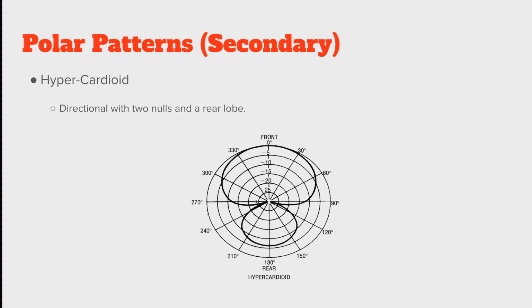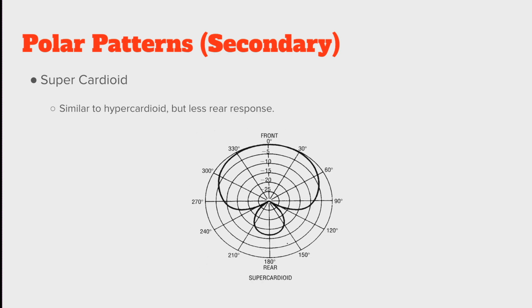Now the front lobe has a little bit of a cardioid shape to it. So we can kind of see this as a combination of a cardioid and a bidirectional microphone. And incidentally, we call this particular pattern hypercardioid. This is a pretty common microphone diaphragm type. I think in a lot of directional microphones, we will regularly see cardioid and hypercardioid.